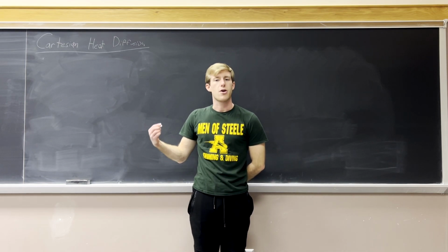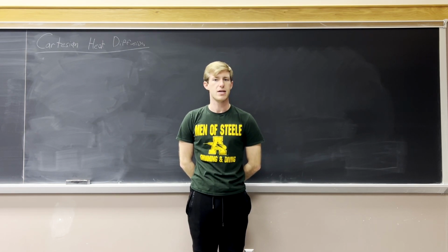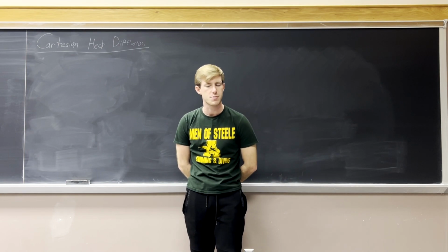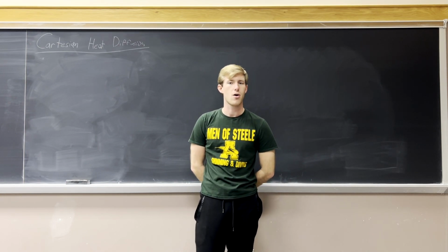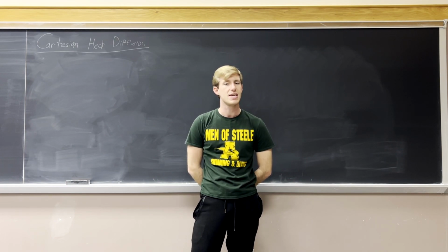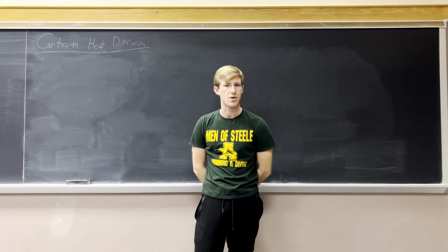Today we're going to be talking about Cartesian heat diffusion, which is to say we're going to take an imaginary sample volume of some substance, pour heat in, a heat flow, in from all of the three directions. Cartesian means a three-directional linear 3D space. So we're going to pull it in from all three x, y, and z directions, and then we're also going to take into consideration any heat that's generated within the function and any heat that is stored inside the function.